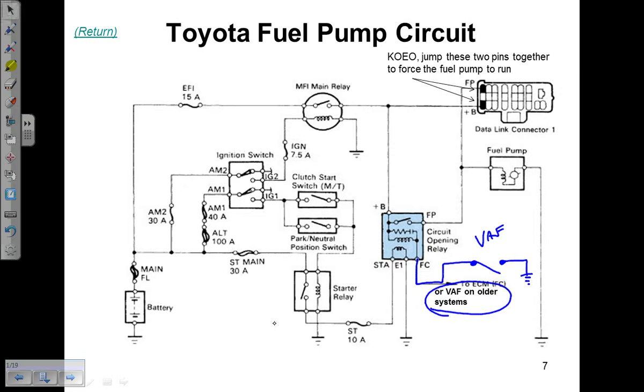And the way the circuit worked was during cranking, and that's this starter relay down here. During cranking, this switch provided power to this coil. So during cranking, it actually was done through the starter. The starter circuit, during cranking, would energize the control side of the relay, would latch the switch, and this coil would get power. But as soon as you let off the key, this would no longer be there. This coil would collapse, because again, this comes through the start circuit.